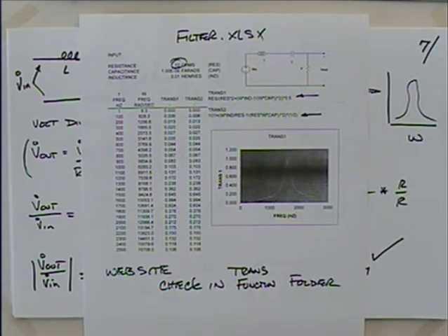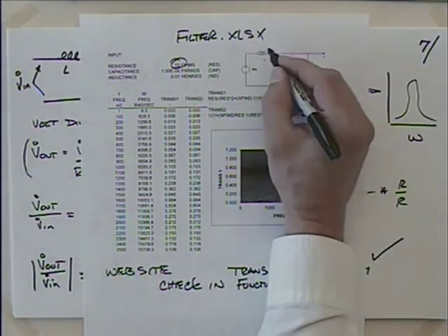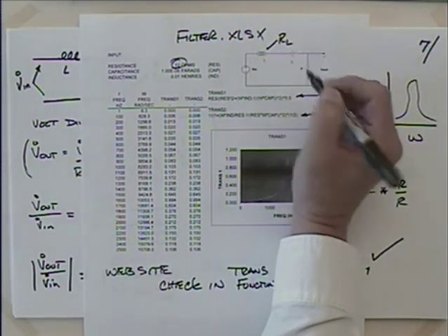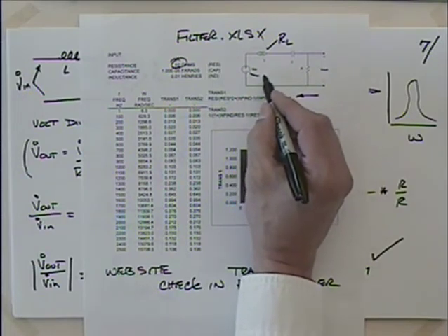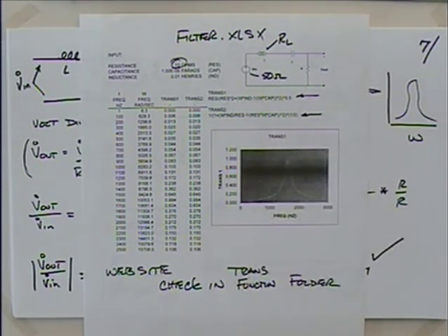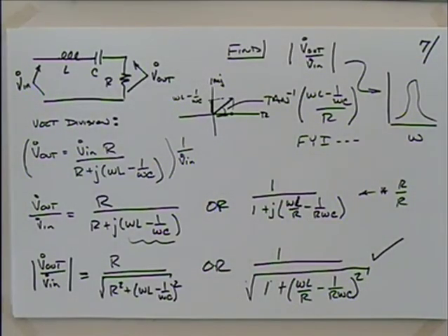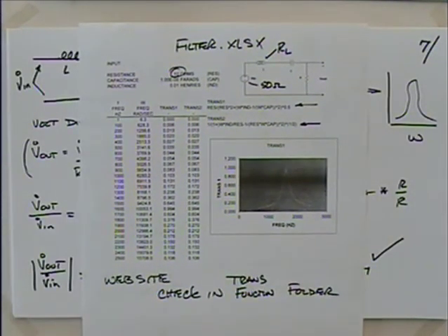Now we're going to be building filters later in here, and when we go down there, we're going to find that the resistance in the inductor is usually pretty significant. There'll be some RL that causes problems. Our source, what was our source down in the lab? I think we had 50 ohms in that thing, so it may not be very realistic to have 10 ohms there. So start putting 100 or 1,000 there and seeing what you get, and the filter is going to change quite a bit. We're going to be doing a lot of this throughout the term, coming up with these transfer functions and using them to model the circuit.